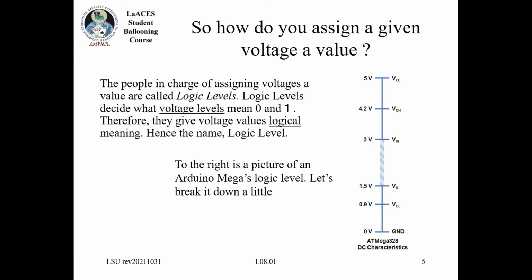I forget what the second T stands for. But there are many other varieties of logic level. There's a very common 3.3 volt logic level. There are other 5-volt logic. There's like CMOS logic levels, and they're going to be slightly different.